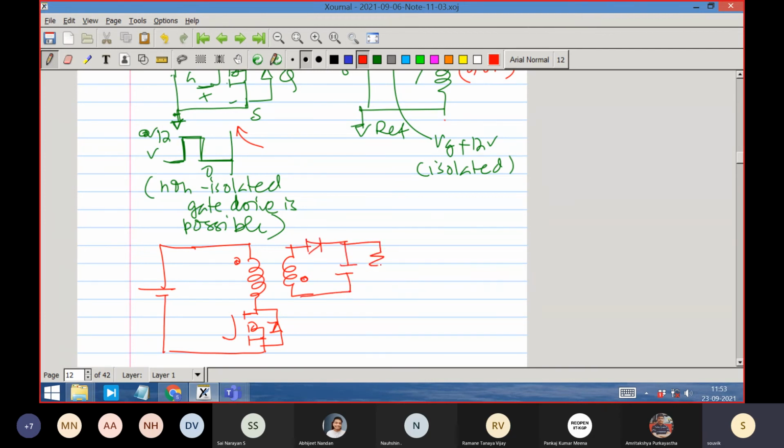this will be the flyback converter we will see, with plus minus V0. This plus minus V0 is truly plus minus V0. This is real plus with respect to this reference, and this has a different reference. So you really are not required much extra component. You really require only one coupled inductor, 2 coil coupled inductor, to isolate this, to produce this isolated topology, the flyback converter, from the core topology of buck-boost converter.